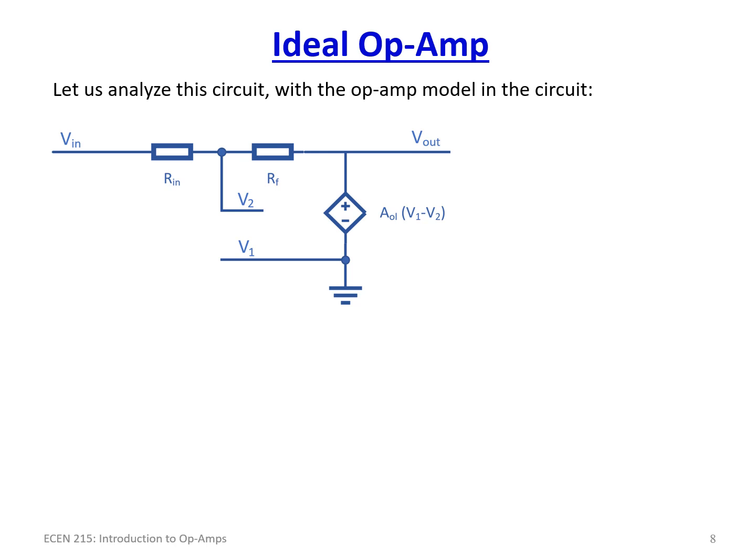So first thing we notice is we can start writing the equation immediately for V out. That one's pretty easy. V out is simply equal to AOL times V1 minus V2. We know that immediately. So let's go ahead and write that out. What else do we know? When we look at this, we have V1, we have V2, and we have V out. The only thing we don't know is V2, because we know what V1 is. V1 is 0 volts. It's ground. So we can go ahead and put that down.